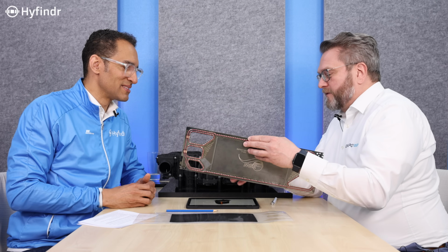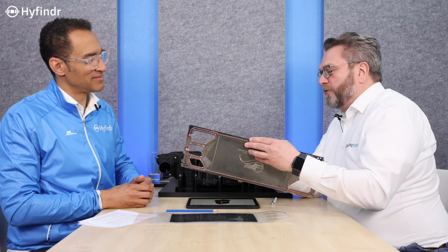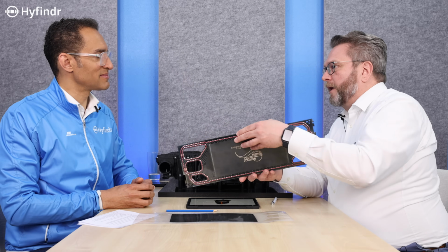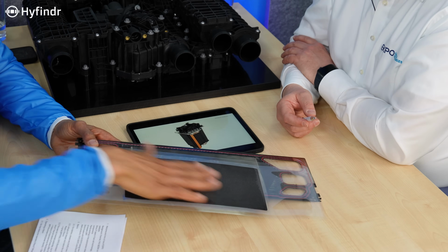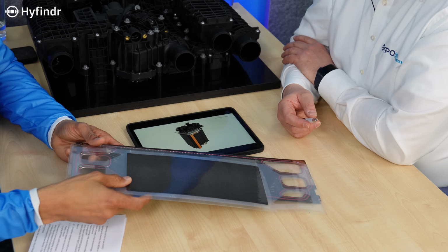Okay, so there are some limits. Yes, we test this. All of the stacks are tested to the limits, and depending on the stack design, we can go up to 30 degrees inclination in all directions, so we give enough space for uphill, downhill. Your challenge in operation is obviously to always supply the entire area nicely with all the reactants needed, so that you have a nice uniform reaction and good performance. This is mainly in the design of the bipolar plate.